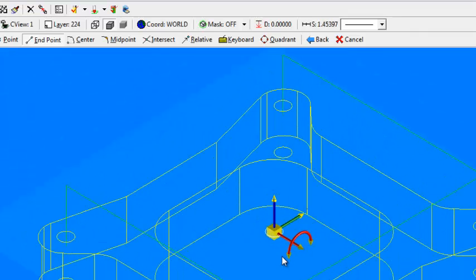Now all those circles do in Surfcam when you drill is locate the center point of the drill. You can put a 1-inch drill through that 3/32 hole. It doesn't care. It doesn't size the drill according to the wireframe.